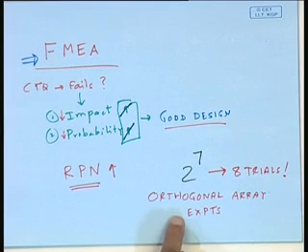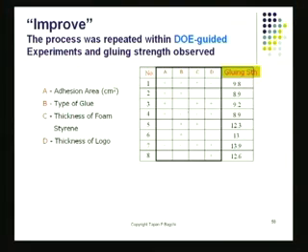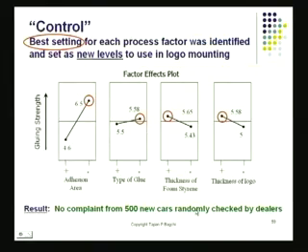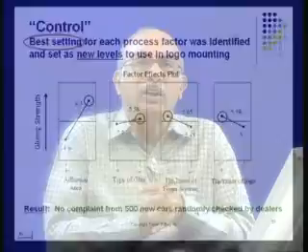This is the framework for conducting your DOE. And that's what we see when we look at the matrix here. This matrix here is an orthogonal array. And this is good enough for me to calculate my factor effects and to plot these effects there. Of course, I'm not really reaching the ultimate optimum, because that would be one of those 2 to the power 7 combinations that are possible. I just don't have the resources for that.